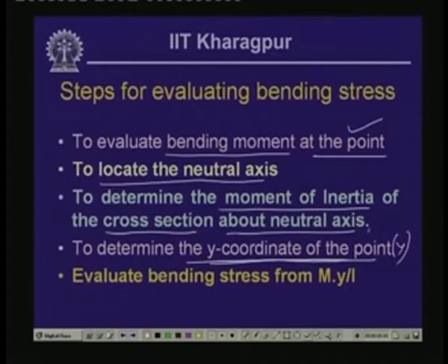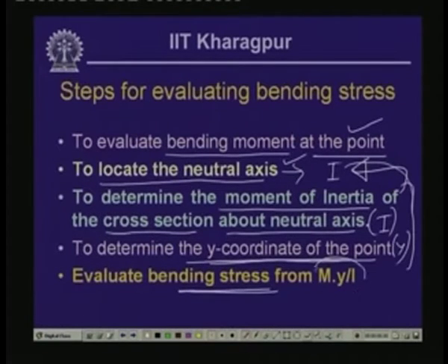So, this is y, this will give us I, and the position of the neutral axis will guide us to evaluate I and y. So, these two parameters will be dependent on this, and once you know this, then we will have to compute the bending stress from this expression, which is My by I. Now, here we can take the appropriate sign of the corresponding parameters and the stress can be computed from this, and we can conclude whether that is a compressive stress or tensile stress that is acting at that particular